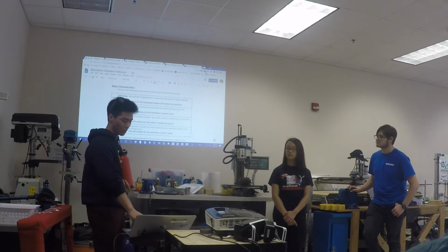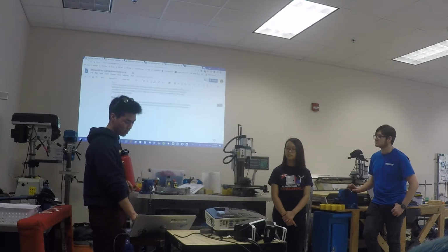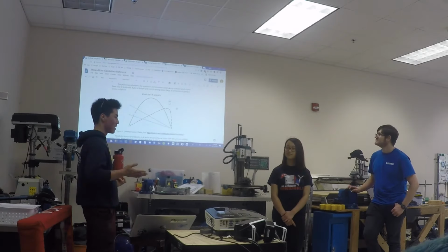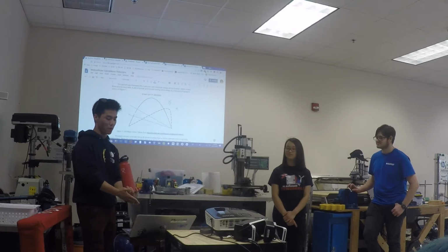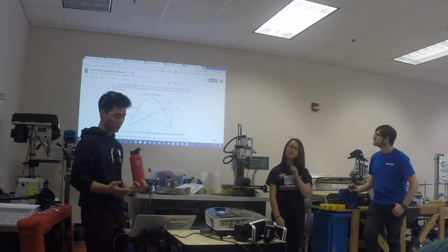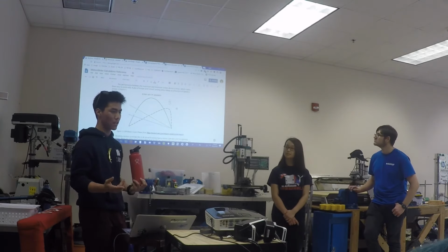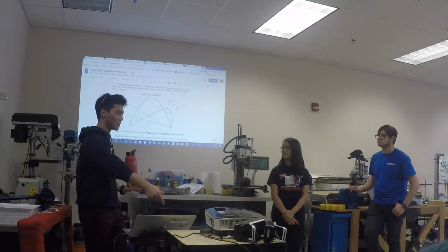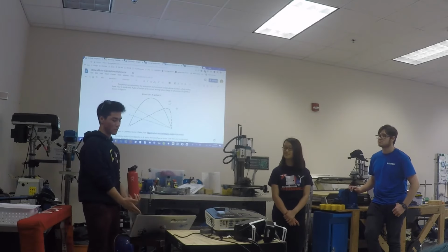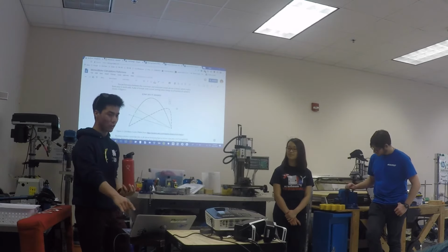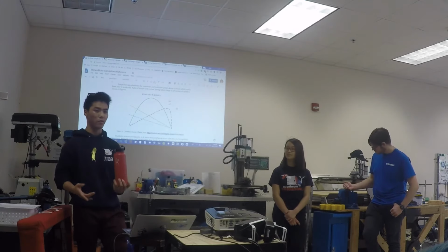And you will start reading things like motor curves, lovely motor curves. These tell you, at a specific torque, how much current you are drawing or how much speed you are getting out of the motor. You can just take a motor and say, this motor produces this much torque, let's stick it here, it produces enough torque for this application. On the other hand, you can read these motor curves and actually optimize it for your use.